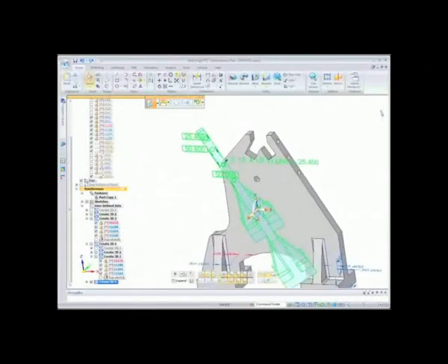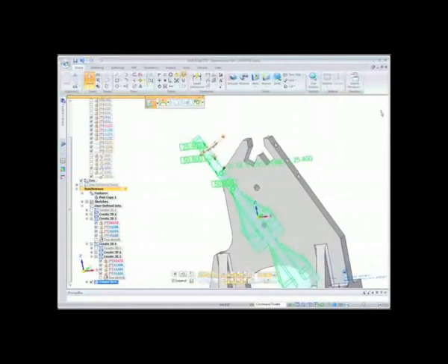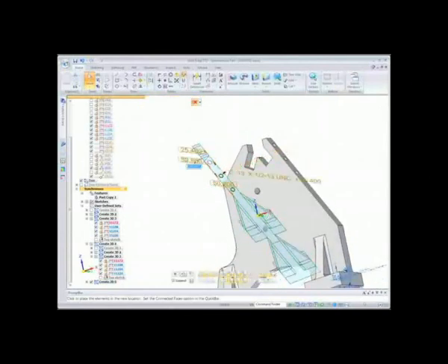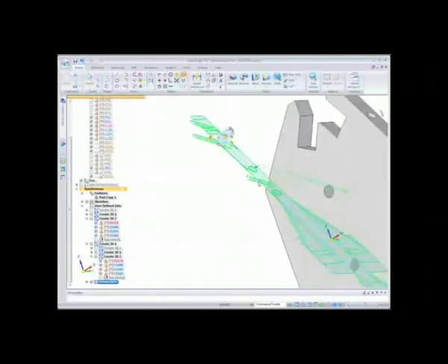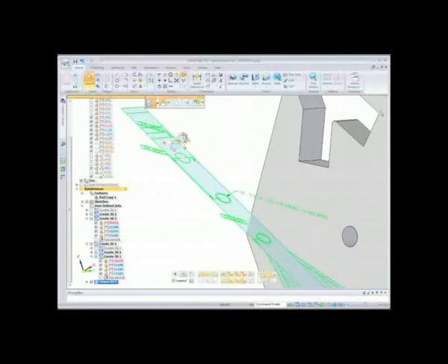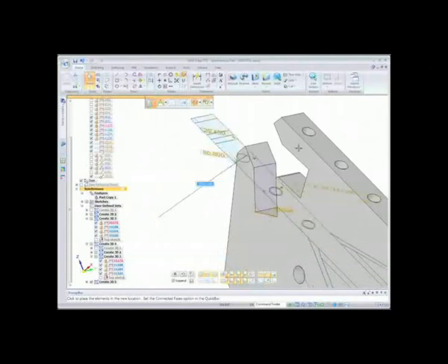Now what I want to do is actually manipulate that to get it in the correct orientation because it brings it in relative to its origin. Rotate it 90 degrees. Then I need to change the orientation of the steering wheel because what I want to do is put that steering wheel centered on a hole and then use that to align to a hole in our model.